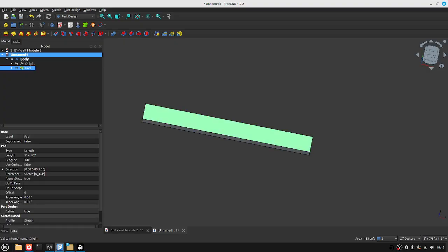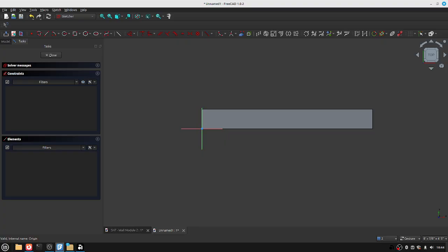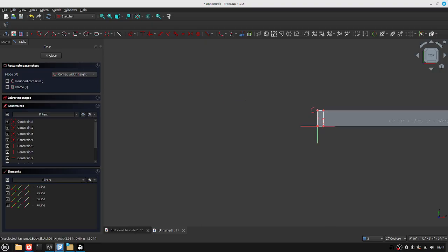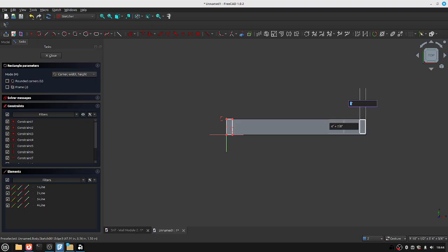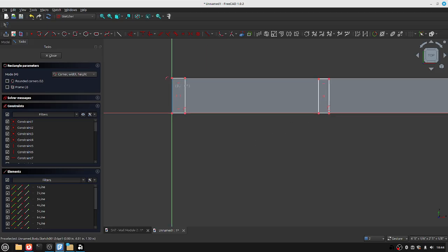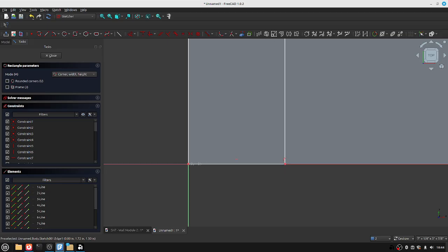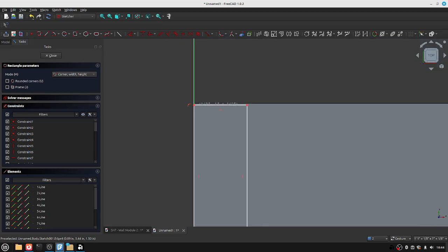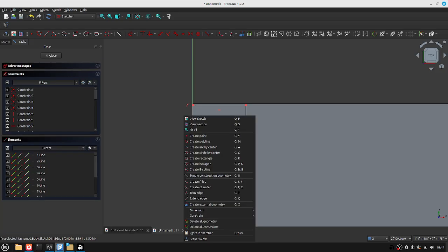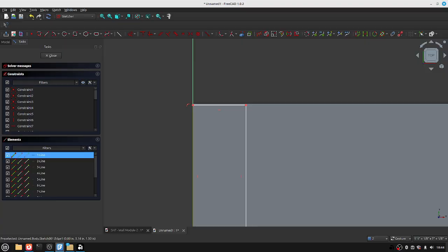And what I would do here is I would just go on top of that and draw myself on that face. I would draw my 3 studs. I will draw this one here. That's about 1.5 inches. I'm just going to do it roughly. But you can now take each of these and constrain them exactly. For example, you can select that height to be 5.5. If you go into the constraints, you select that dimension. What do we want? That would be 5.5. Oh, it's already 5.5.